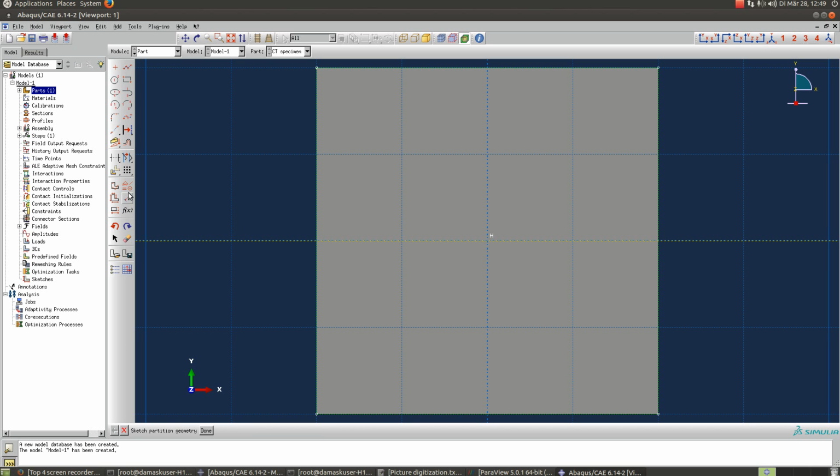Make it fixed, just in case it moves in the future. And what I want to do is create a partition here. For example, if this part is welded, and the rest is base metal, so for this case I want to mirror it. It is asking me if the type of mirror is copy. Yes, it is copy. Pick the mirror line, I pick this, and then select the entities to mirror, and I pick this, and there it is.